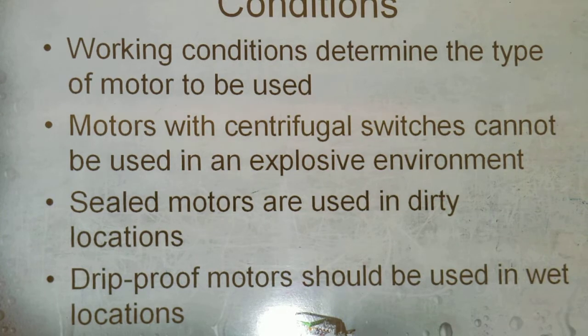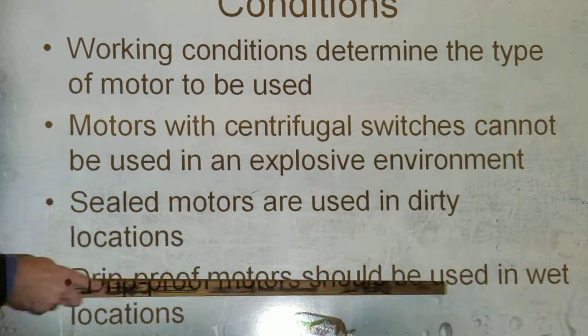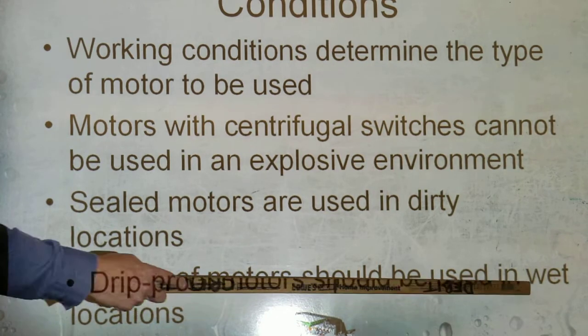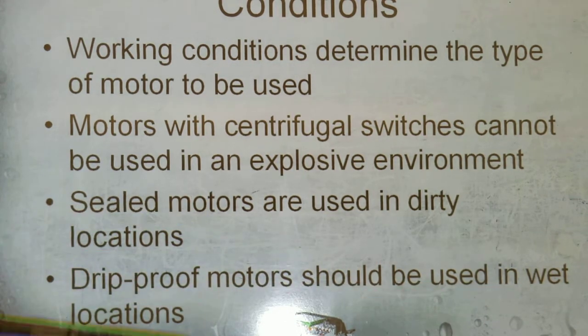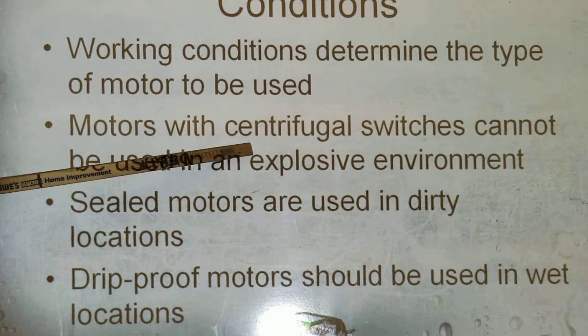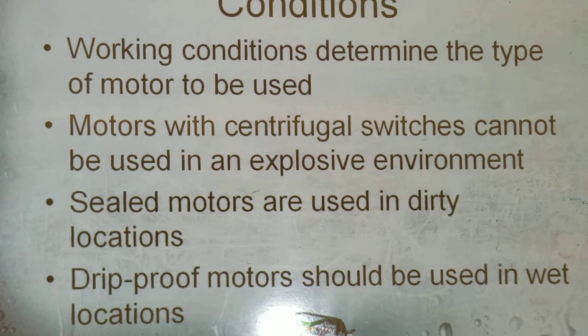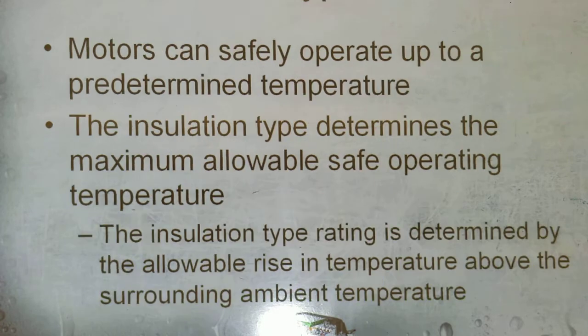Okay, so you remember some of these questions from last week. Drip proof? Wet? Sealed motors are used in dirty locations. And centrifugal switches, because they spark, you're not gonna wanna use them in a gas station, right?